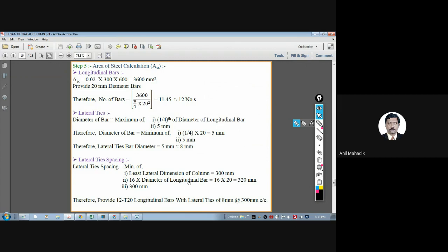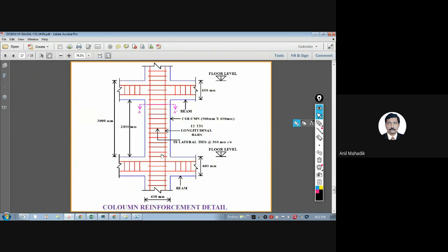बीम जंक्शन के पास स्पेसिंग कम रहता है, top or bottom कम रखते हैं. हाँ, तो वो आ जाएगा. I think that will be discussed in earthquake design. Whenever you do the ductile detailing, we keep the spacing closer, 150 or 100 near to the beams.